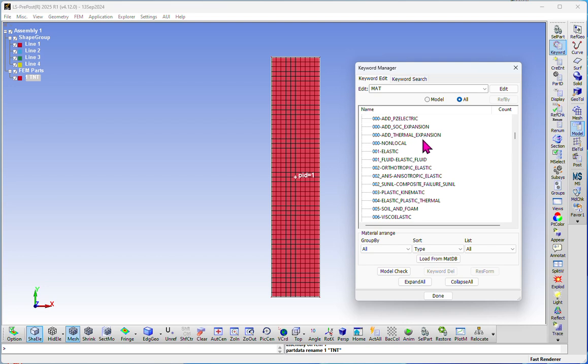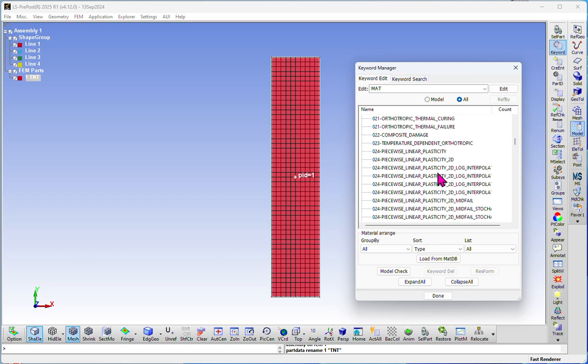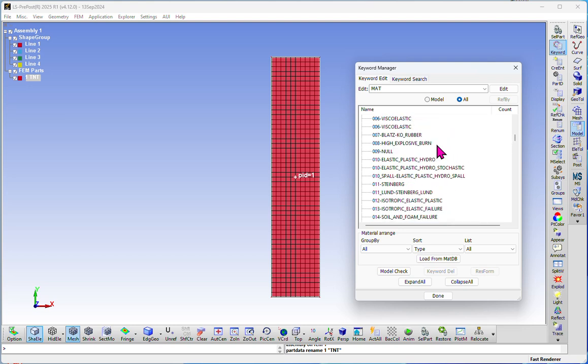So if you look, there's elastic. So if you have something that's elastic, it's there. Plastic, kinematic, and there are just hundreds of options to make a material behave the way you want it. And so much of doing a keyword input for a model is filling out the various mat properties that you need, and periodically an EOS is associated with it.